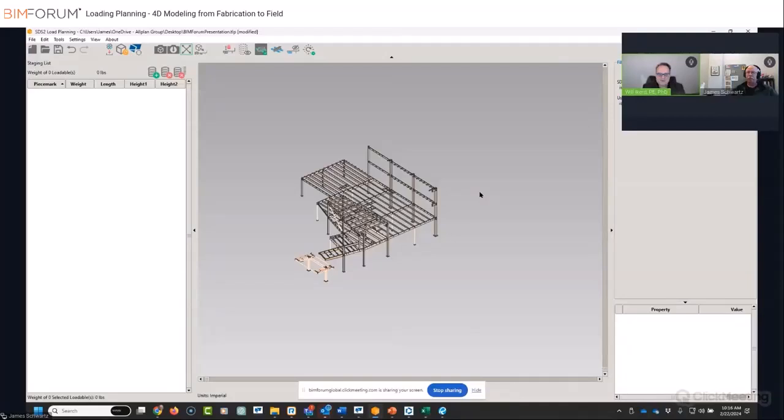So your sequencings will normally include some vertical zones. And that means you need to sign off MEP coordination everywhere the steel is within that sequence. So if you're down in the basement, you're moving to the first floor, but your steel sequence on the first floor goes up to the third, there's still some coordination where you have to jump up ahead. So the ability to have tools like this that can show you what steel is released, where it is in shipping, what's on site, I think are going to be really valuable as teams are trying to compress their coordination of MEP with those tie-ins.